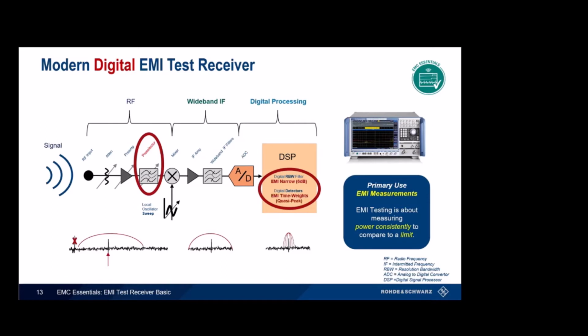The last change is to the LO that feeds the mixer. Here we'll add a stepped scan function which enables a step scan of the EMI measurement.